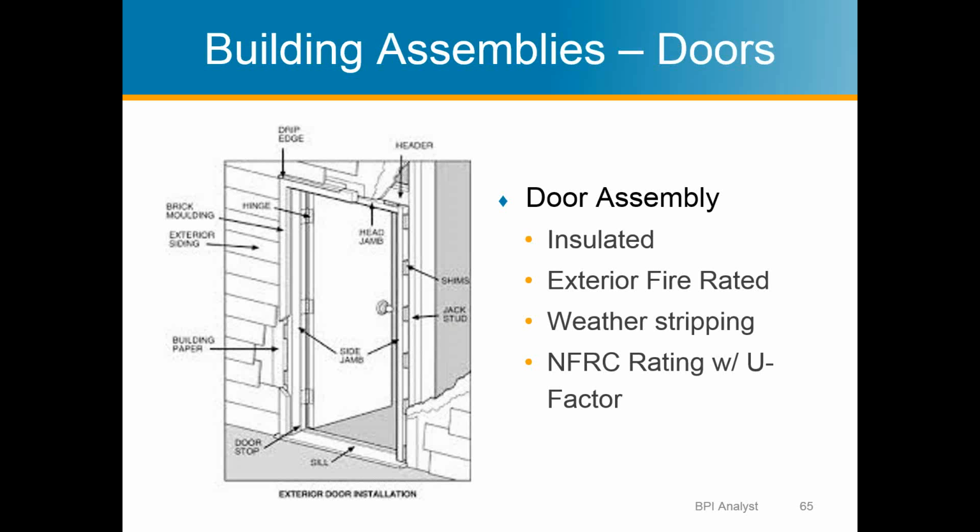But I think the main reason why we don't hear a lot about doors and high performance doors is the area of all the doors in the house is pretty darn small compared to windows in the regular wall. So greatly increasing the R value of the door doesn't give you a whole lot. What you do want to pay attention to on doors is just the weather stripping and the seal. The airtight seal in that door is probably the most important thing to pay attention to. Not necessarily the door itself.